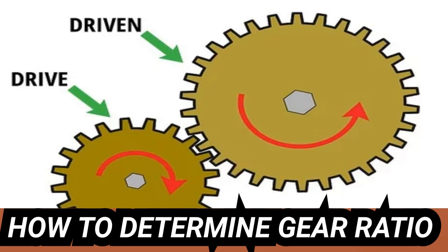Video. Tips. The power needed to drive the load is geared up or down from the motor by the gear ratio. The motor must be sized to provide the power needed by the load after the gear ratio is taken into consideration. A geared-up system, where load RPM is greater than motor RPM, will require a motor that delivers optimal power at lower rotational speeds.